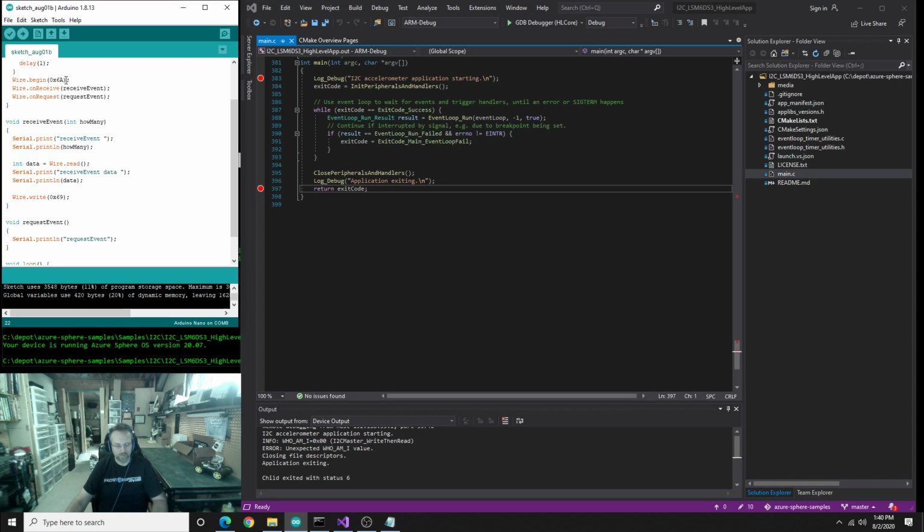When you're receiving, that's where there's an address line of 0x6a, and it's sent out. We said acknowledge, the Arduino said acknowledge, and then it sent out a certain number of bytes saying, I want to do a write, and it wrote out that many bytes, which we were able to read. Then it sent out the same address, 0x6A, and it said, I want to do a read of a byte. And so there was this request event that we saw, and we printed out request event. And that's, during request event, that's your time to write back answers to those requests.